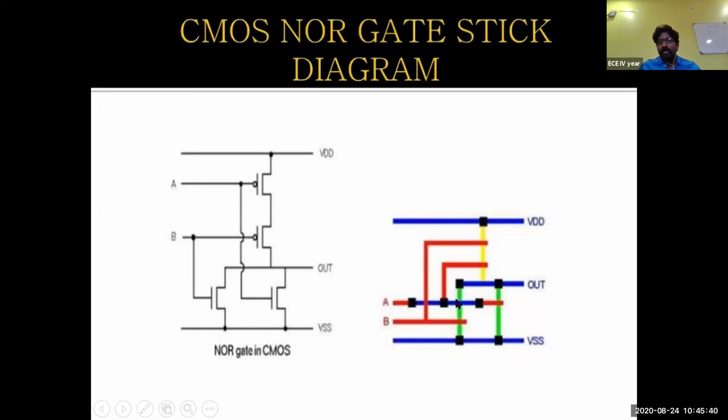If you draw the polysilicon upon this diffusion, then again it becomes an error, because any diffusion will have only one polysilicon, which represents one complete transistor. We cannot draw it like two input transistors. Even though there are different kinds of structures which are used, as per this particular design we cannot draw this polysilicon again upon this one. So they have used a metal layer to make this connection.